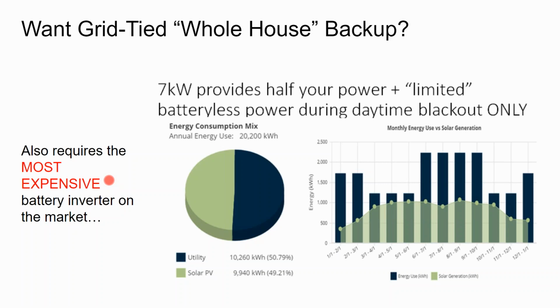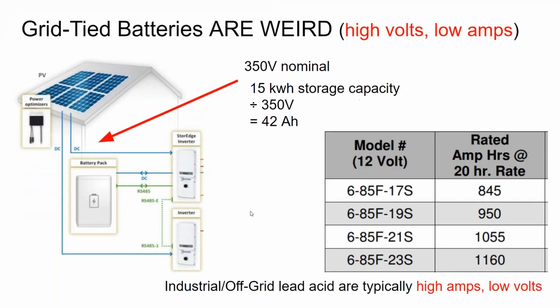And then they have to have all the listings, and then you have to have all the critical load infrastructure on top of that for something that can only protect critical loads and not really power the entire house, unless you trick the system into allowing you to use the critical load power and your solar array power at the same time. But that's going to void your warranty. And so it's not only a not satisfactory solution, it's also a very expensive solution.